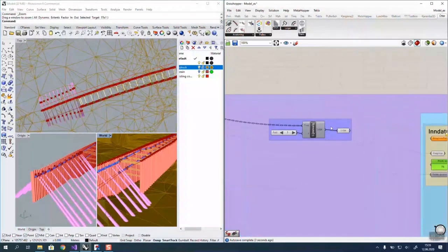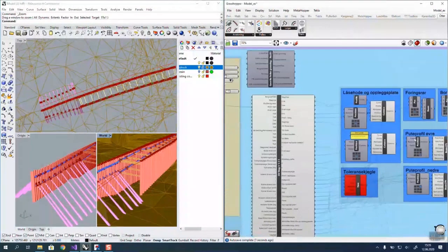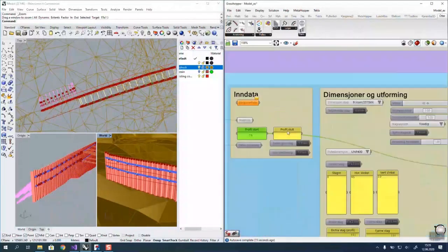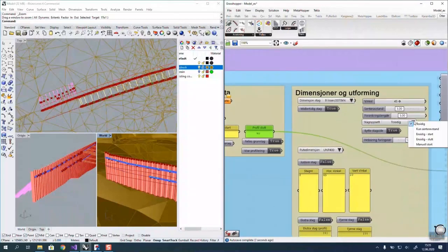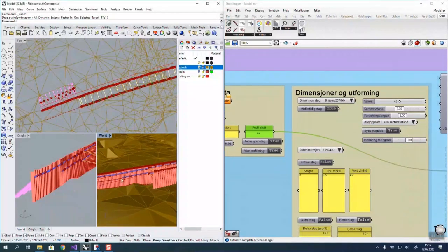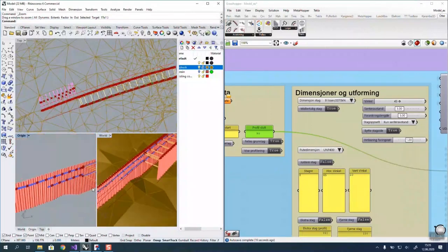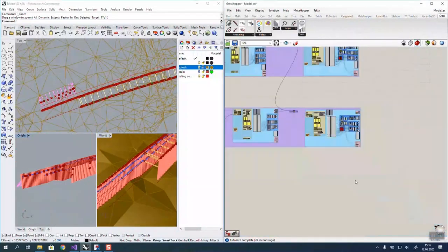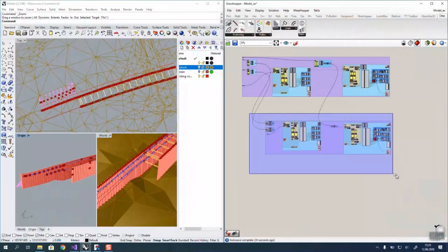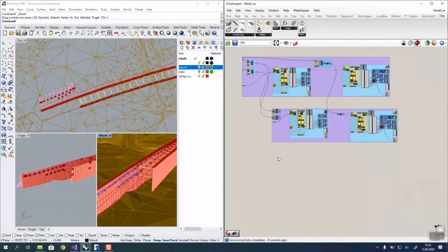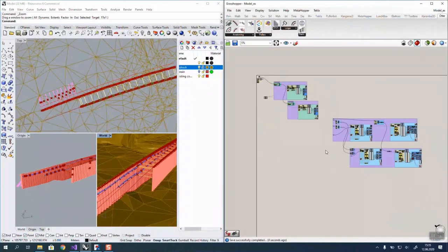And now we just did some copy paste of the strut and anchor scripts just to get this full construction pit with a double level strut and anchor systems. So on the level 2 anchor row, you see we want it a bit shorter, so we could easily adjust that as well. Okay. So then it's actually finished.